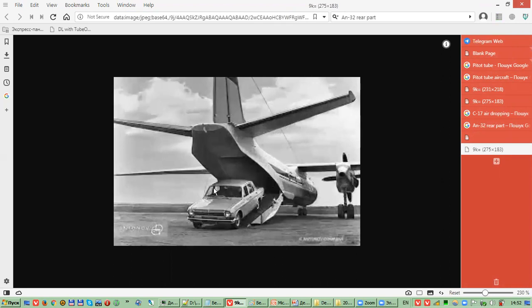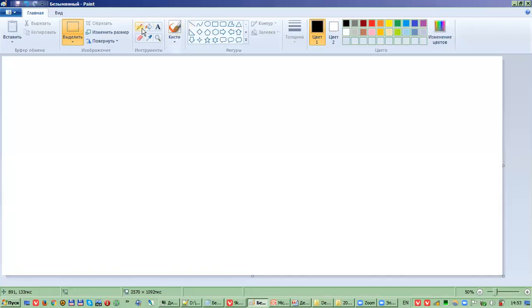This is also the rear end of an aircraft, cargo hatch, ramp, and also two vertical strakes. This is not for stability and control. These strakes are only for air dropping cargo. These strakes create two vortices, air moving from external to internal. And these two vortices, wait a minute, I will make a small picture. Vortex 1, strake 1, strake 2.